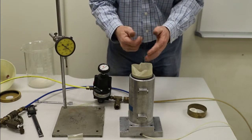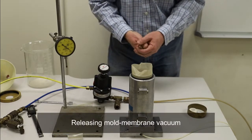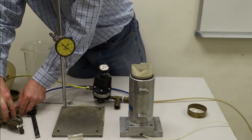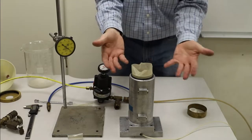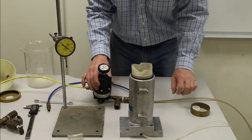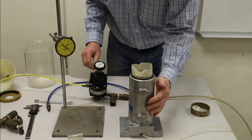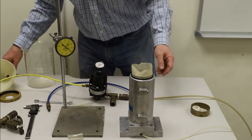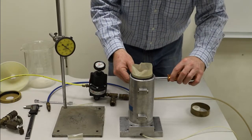But now that we have some confining stress, we can release the vacuum that's on the mold. So we'll do that just by unplugging it from the source. We can't see anything happen because it's within the mold, but as long as we're confident that we have vacuum going to the inside of the specimen, we believe it should be okay to take apart the mold.